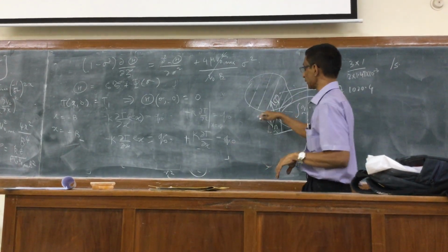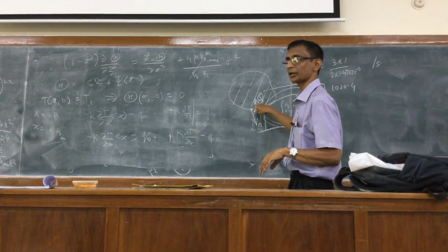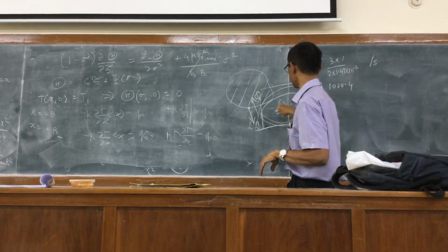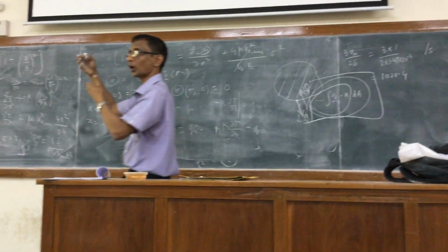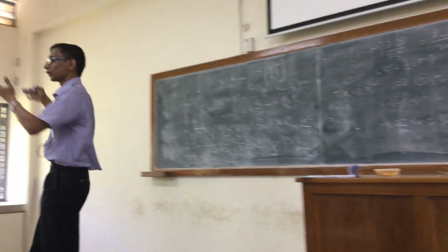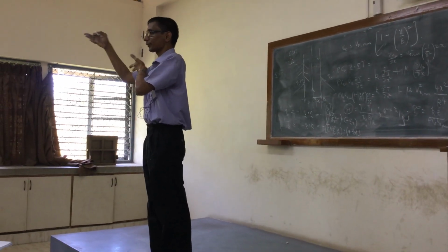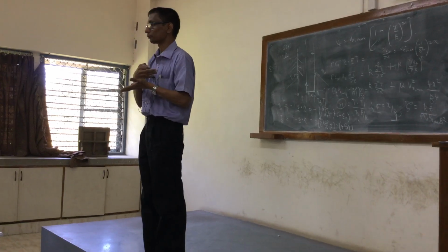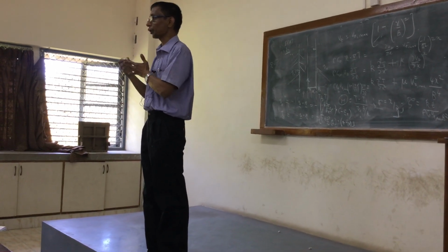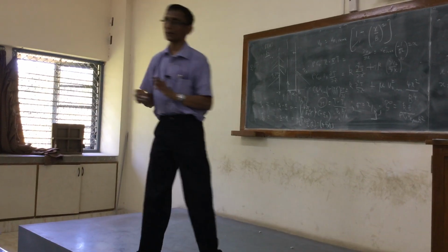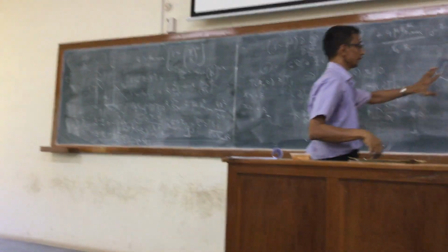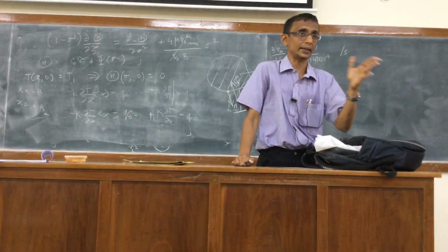So I am identifying here by inject. This is to be calculated at every point. At every point the heat that is transmitted is minus q dot n. The n is the outward normal coming from the body to which I am considering the transfer of heat outward. And for q, it could be Fourier's law, it could be any other law. But you have to understand that finally minus q dot n effectively represents the net heat in.